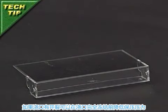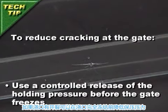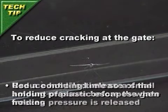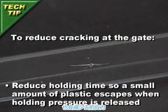If cracking at the gate region is a problem, it can be minimized by a controlled pressure release of the holding pressure shortly before the gate freezes, so as not to overpack and overstress the gate area. Another technique is to reduce the holding time so that a small amount of plastic escapes from the gate area when the holding pressure is released. This will also reduce the stress in the gate region.